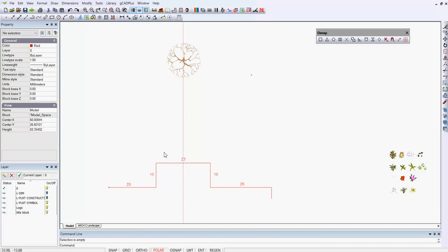Well, I've had a request to go more slowly over placing those lines, placing the footprint of the house down again. So remember, we went draw, line, and the prompt down in the command area and also at where the mouse pointer is, it's saying first point, and I typed 0, 0. That's 0 on the numeric keys across the top of the keyboard. It's not capital letter O. Then I hit the enter key. Now when I move, you can see I'm anchored at that 0, 0 point.